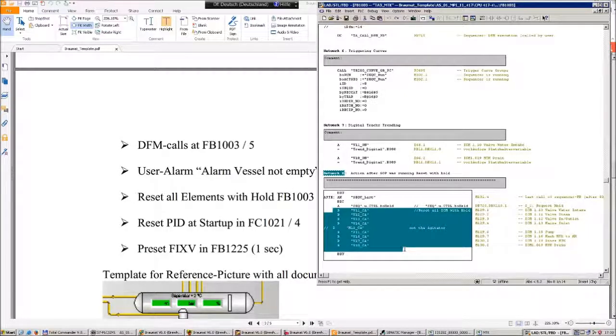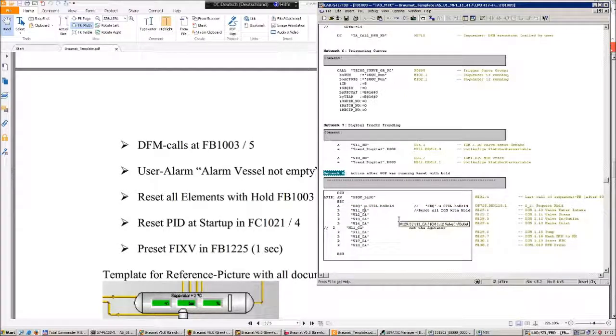then you reset all the elements which belong to the unit. So this is the easiest way to ensure that in case something is wrong, for example in CIP, the CIP program is running, and after 1 minute the caustic is not coming back, then you have a problem. The caustic is going somewhere, but it's not going back to the CIP plant, and then you should stop the process. It could be that the caustic is going to the tank, to a product. So when you're sending something, it should come back. And if the operator detects it's not coming back, then you should switch off everything to verify what is going on. And this can be done by this programming. You identify the command automatic signals which are used in this unit and reset them in this way.